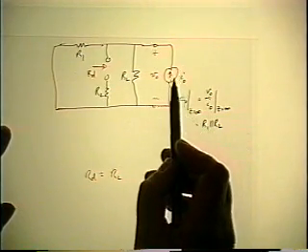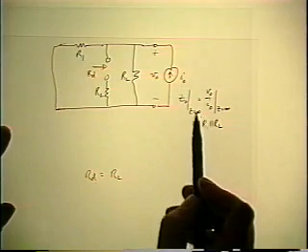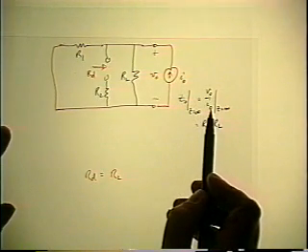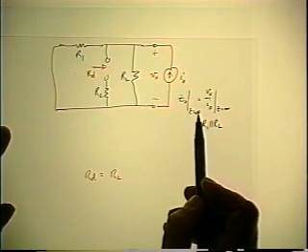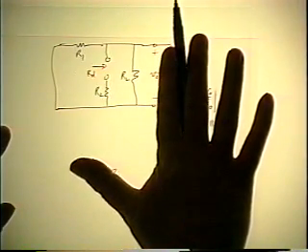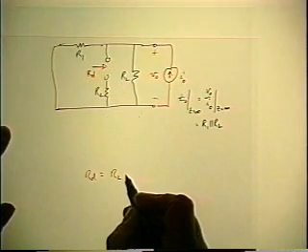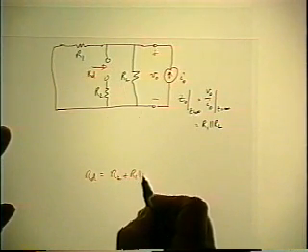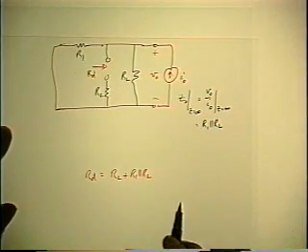And the correct identification of the input is I_O, because that's the quantity in the denominator of the transfer function. So if I_O is 0, that current generator is gone, and so you're going to get R1 plus R_L for the R_D.